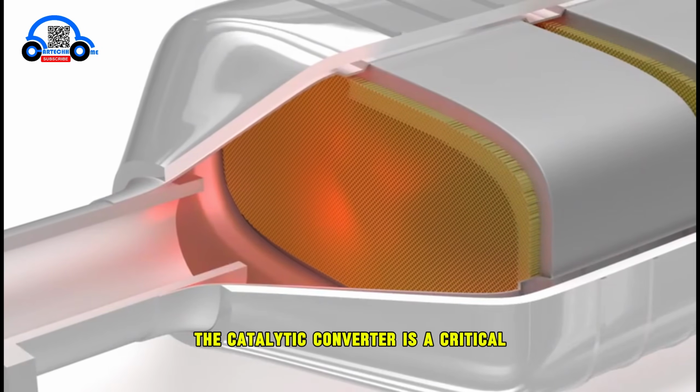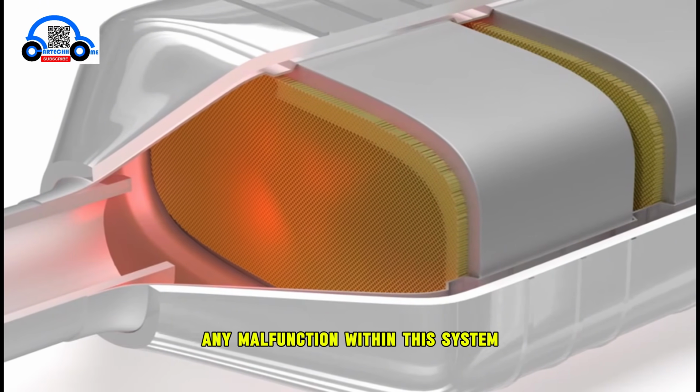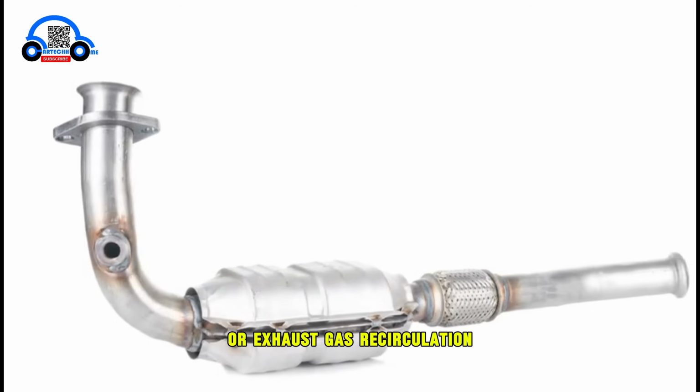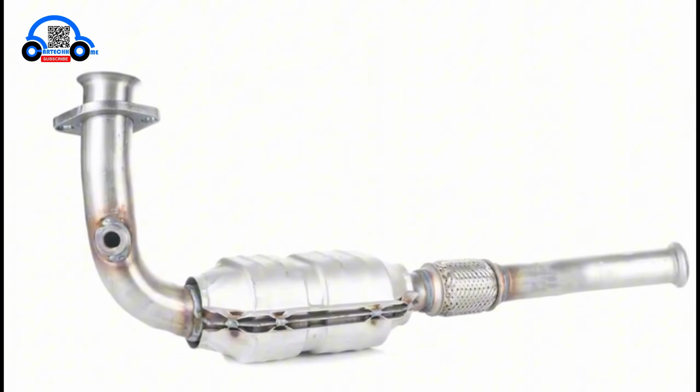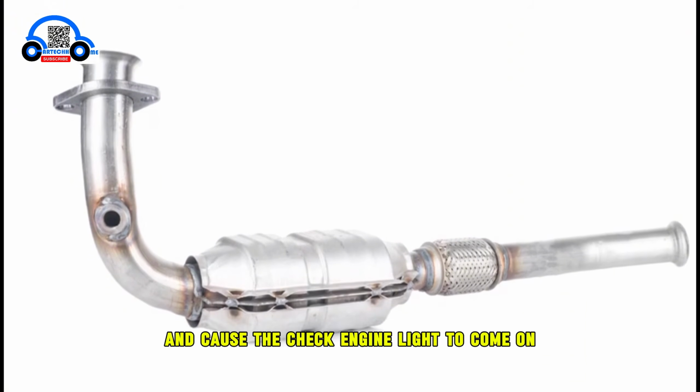The catalytic converter is a critical component of the vehicle's emission control system. Any malfunction within this system, such as issues with the air-fuel mixture or exhaust gas recirculation, EGR, can impact the converter's performance and cause the check engine light to come on.